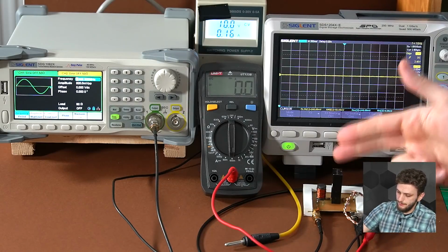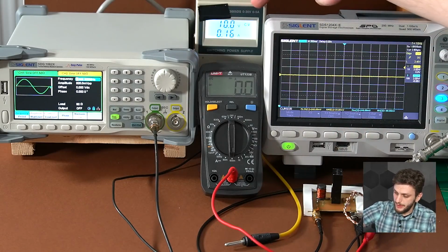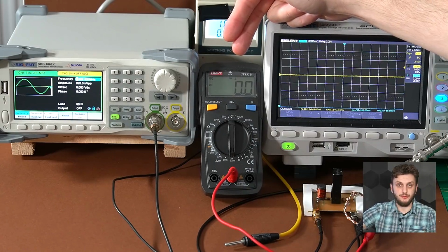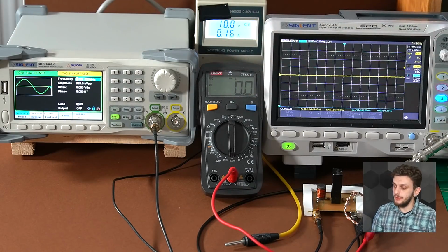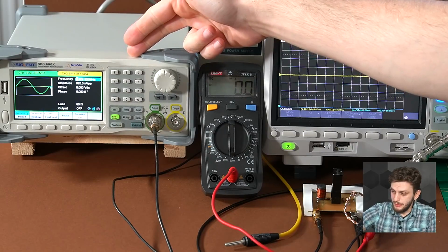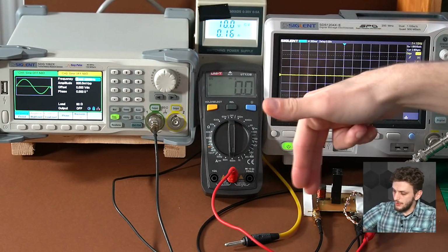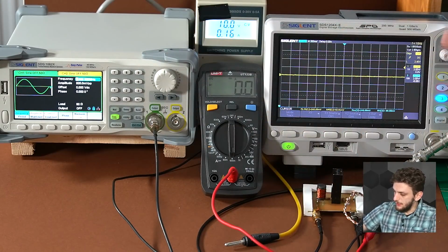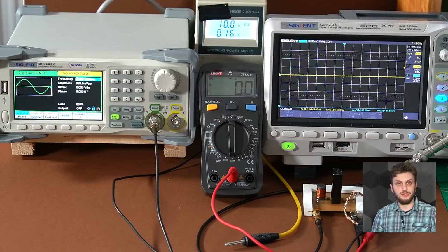I've got my circuit, it's being supplied from my power supply back here, and I'm passing the current through an ammeter to get a more precise current measurement. My signal generator will be providing the signal into the circuit, and the output is connected to the oscilloscope's first channel, where I have my 50 ohm termination resistor.